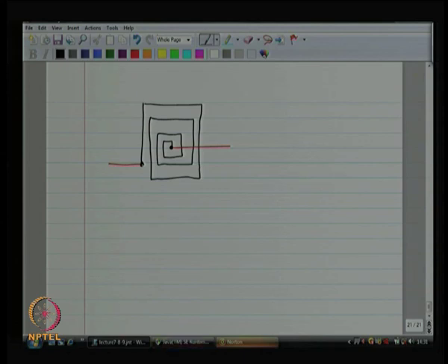Okay. In last class we were working with a circular spiral. Today we are working with a square spiral. Any reason? No reason whatsoever why you might choose one over the other. Both behave perfectly well as inductors. One cool neat thing about the square spiral is that all the coordinates can now satisfy the grid requirements of your foundry. So, the square is quite popular because of that.